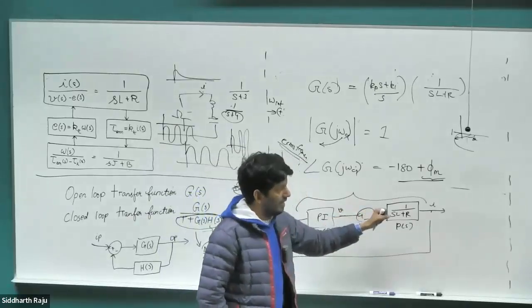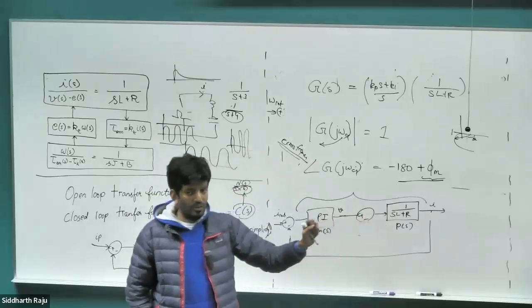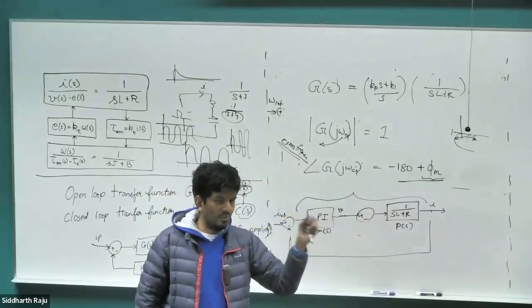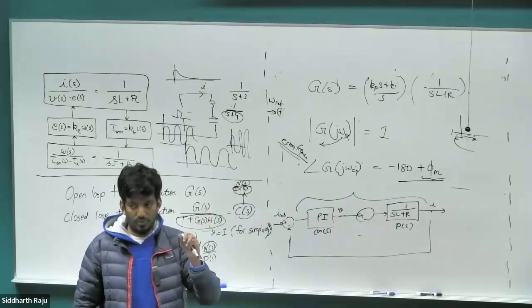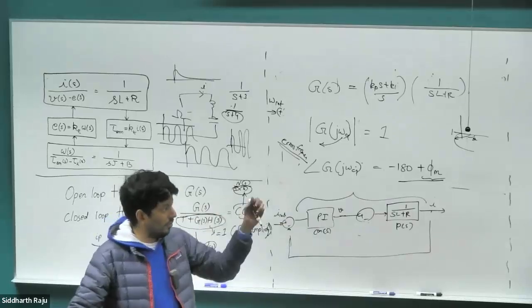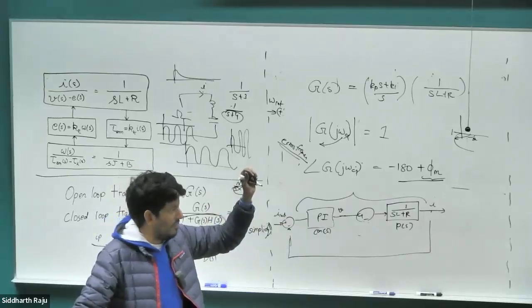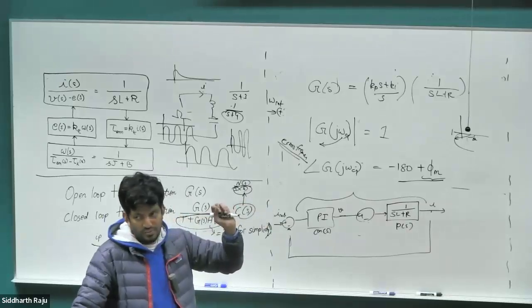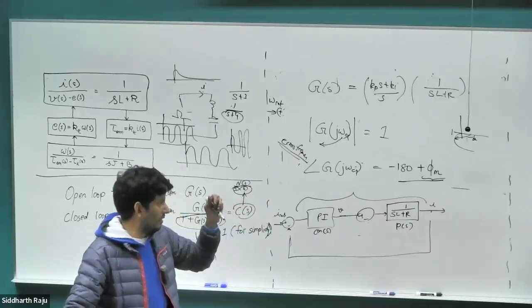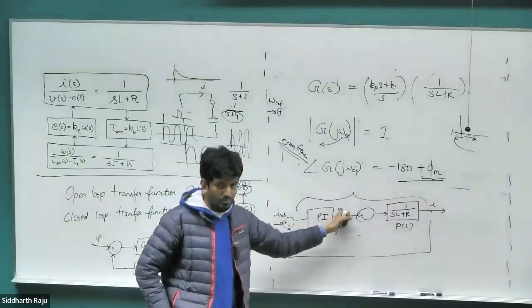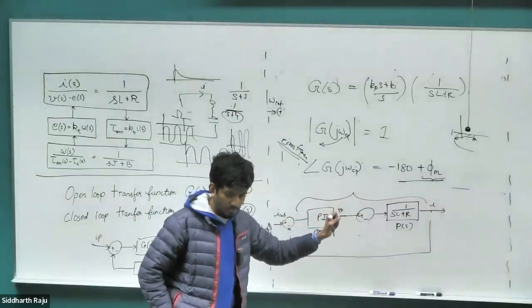Just because the mechanical time constant is low, that does not mean that once we put in a controller, the response time must also be slow. I can design a controller that has a crazy large KP value such that it responds quite fast in mechanical terms. We can even design it so that it responds faster than the inner current loop, right? But that would defeat the whole purpose of doing this.